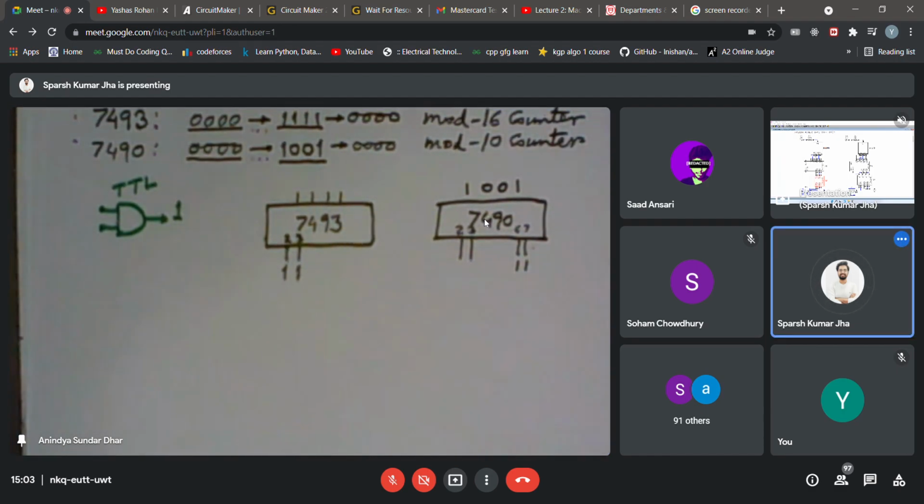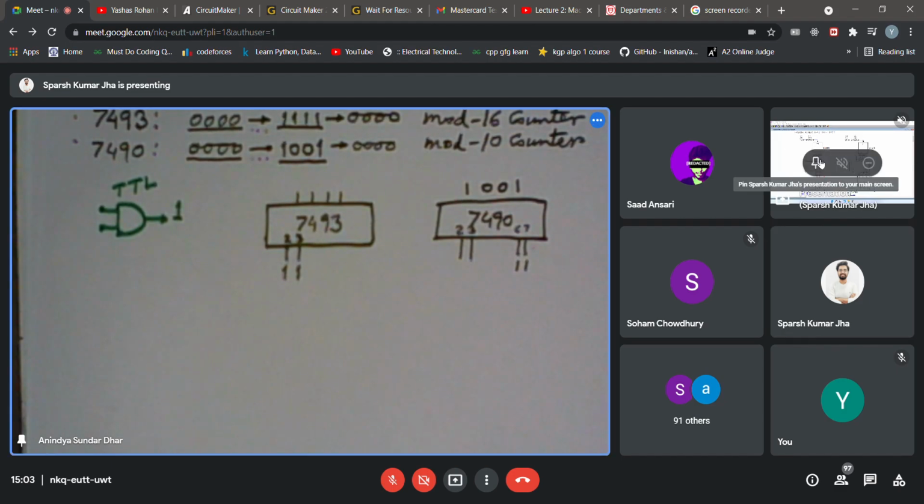Yes, sir. This CP0 is for synchronization, and then the CP1, which is connected to A0, is for changing the bit in Q0, and successively all of these change. If we don't connect this, then whatever the display will be, it will be frozen. It will not move ahead. But probably I do not know whether you are aware of that reason.